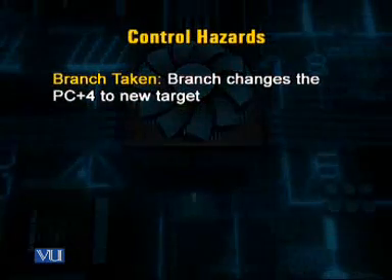But in a pipeline data path, we have to fetch the next instruction in the second clock cycle. So this means that the instruction being fetched during the second or the third cycle from the present jump position may or may not be a valid jump instruction.